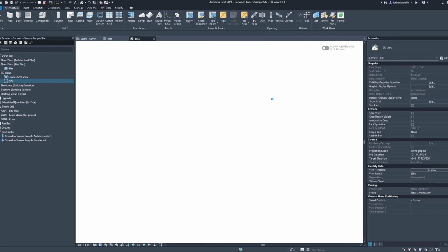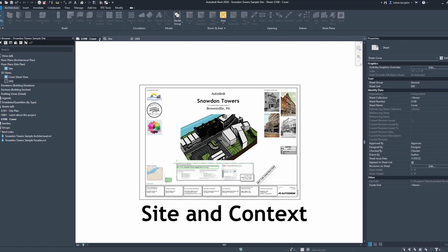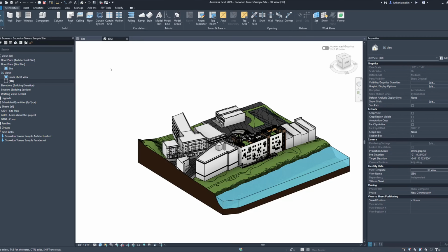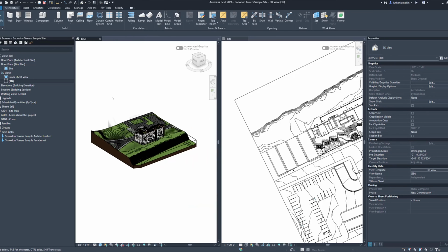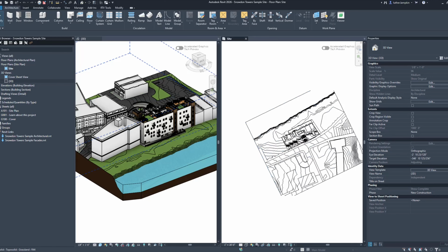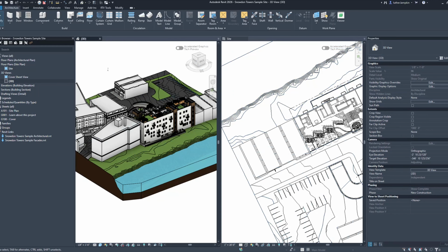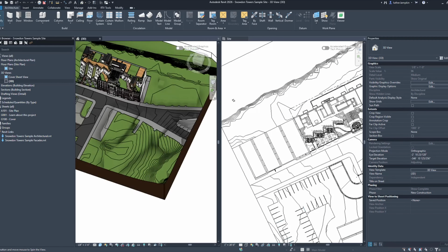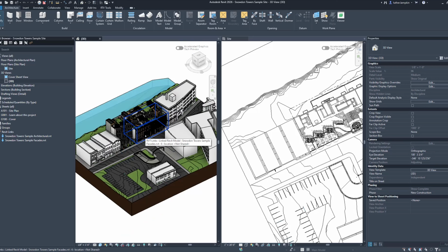All right, it's super important that we look at the model from all areas, okay? And especially with our workflow, I'm gonna make sure we cancel out this cover sheet up here. And then I want you to hit WT, which is window tile. And we're gonna look at these in two different components. So that way we can see everything, and then we're gonna see the same thing in the components over here for the topography surface. All right, when you're in Revit, always remember, we're always going to be working in 3 dimensions and 2 dimensions at the same time. That is utilizing the parametric engine.